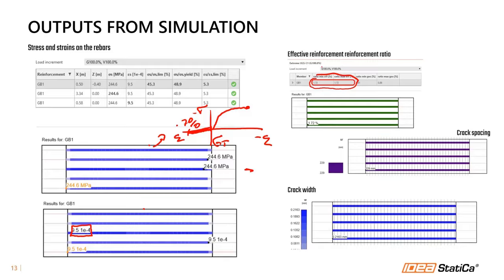So there is just the reinforcement ratio. This is the value. There is also another value, a geometrical reinforcement ratio, but this is not important for our case of the tension chord model. This is for another approach for calculation of low reinforced concrete. It's called the pull-out model or non-stabilized crack pattern. But right now we are talking about the stabilized crack pattern. So we are leveraging this effective reinforcement ratio.